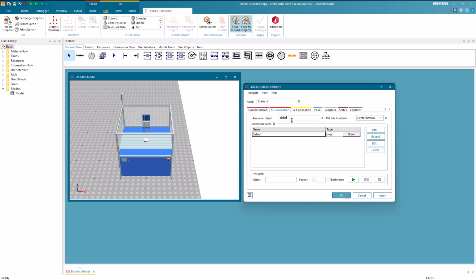Up to this point, we have established a new animatable object that will serve as a means to transport parts. This approach allows us to model scenarios where specific actions, such as safety doors opening before a part moves to the slider for processing, can be represented. To model such scenarios, we have 2 options. The first method involves creating poses and then having the slider move to those poses. Alternatively, we can use coordinates directly.